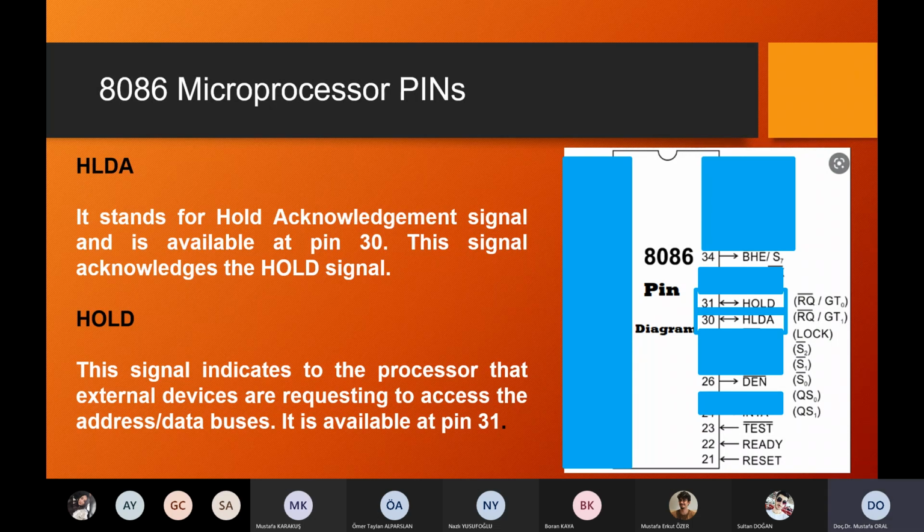We will be talking about this in detail later on. So whenever it wants to reach memory without using the microprocessor, it needs the ownership of the address bus and data bus, because if both of them request a read and write operation from RAM together, then it will be disastrous.